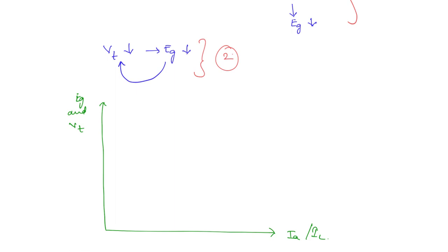Now what will be the characteristic? The internal characteristic is going to be like this. It will fall like this, and in fact after reaching a particular maximum value of current, it will start falling down, okay? So this is the internal characteristic. The external characteristic is going to be further less because of the extra drop in the armature winding, the Ia Ra drop. So this we will draw with a different color. It's going to be like this.